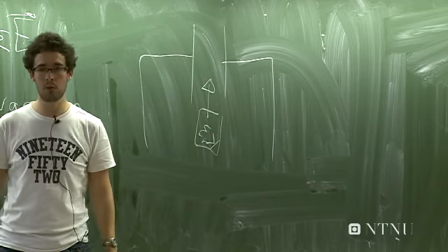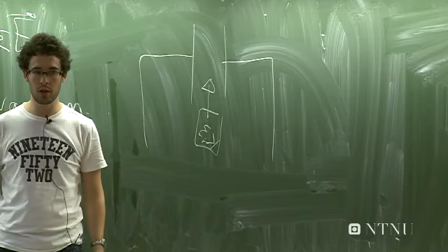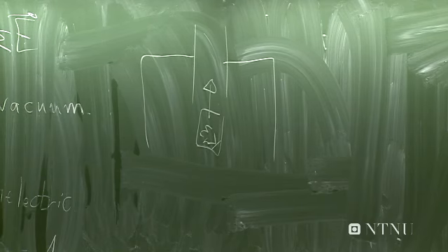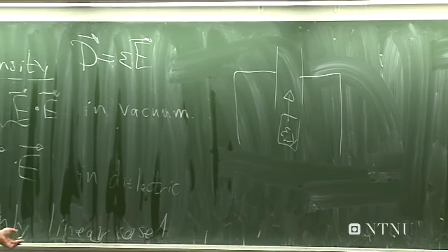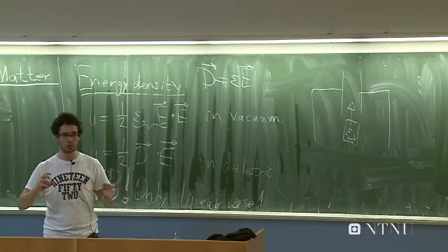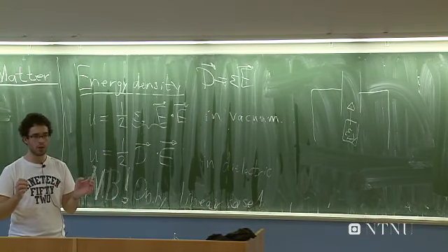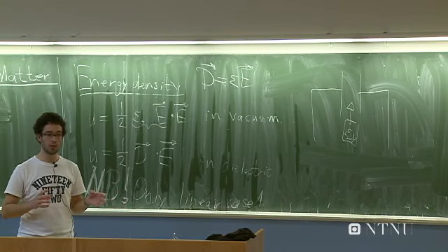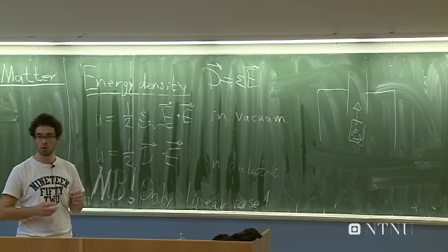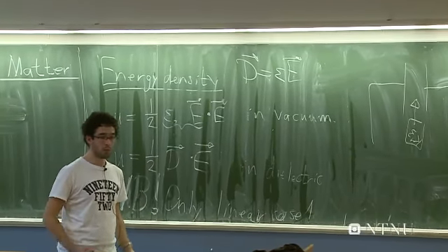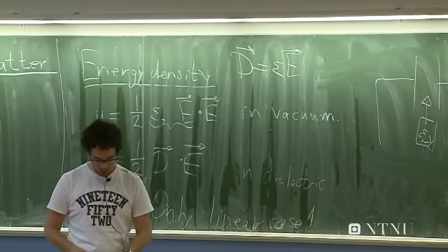with an epsilon r bigger than 1, I increase the capacitance, or the ability of the material to store energy, which of course increases when you induce these dipoles. You need to do work to do that, because the natural state of affairs is of course to have no induced dipoles in the material. So you have to add energy to induce these dipoles. So that gives you a larger capacitance, a larger capacity to store energy.